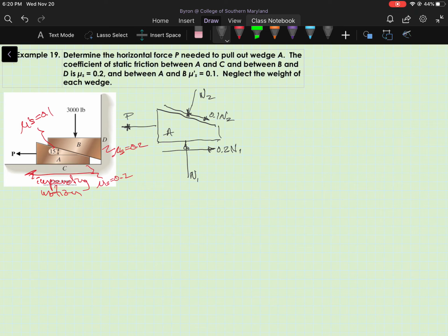So we'll have the two equations, the sum of the forces in x equals 0, and the sum of the forces in y equals 0. And we'll use our standard reference axes. So if I count up the unknowns in this free body diagram, I have 1, 2, 3, and with only 2 equations to work with, we're not going to be able to solve for those 3 unknowns.